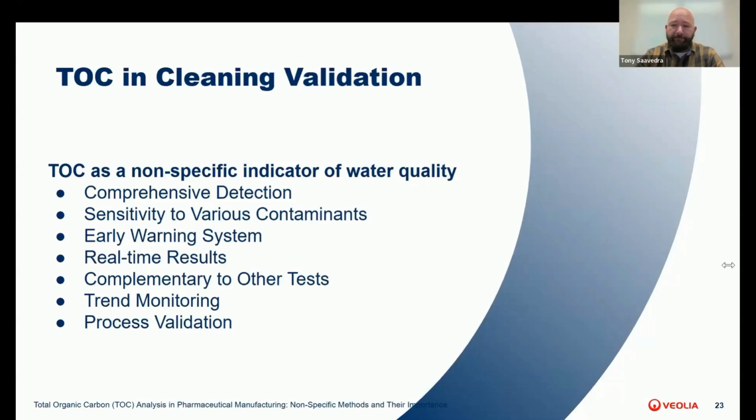Then trend monitoring. TOC is excellent for monitoring trends in water quality over time. By tracking TOC levels, you can identify gradual changes that might indicate developing issues in your water system, such as biofilm formation or degradation of purification media.